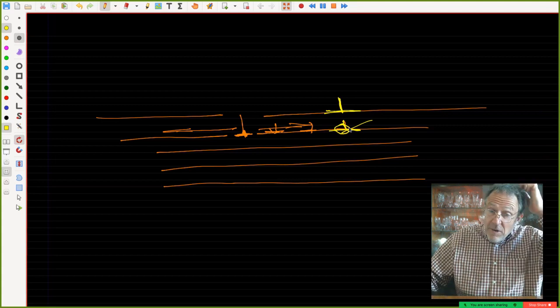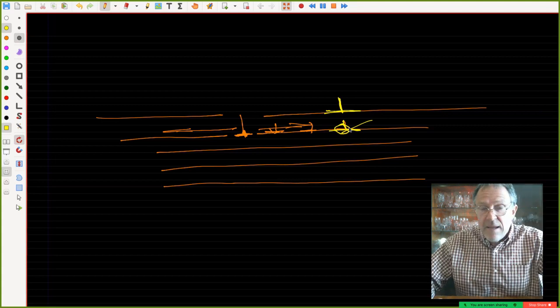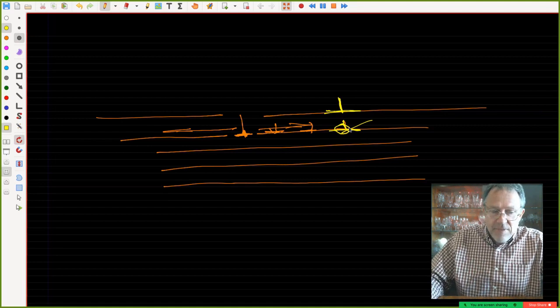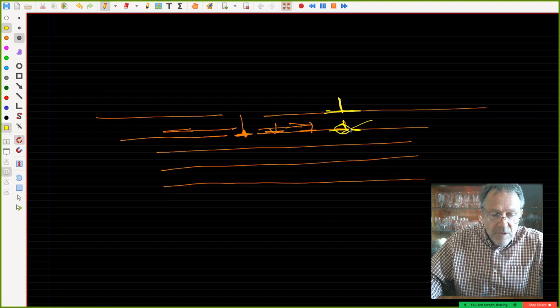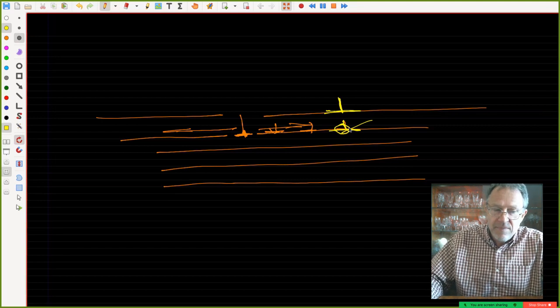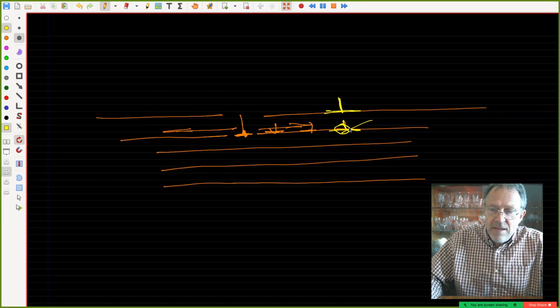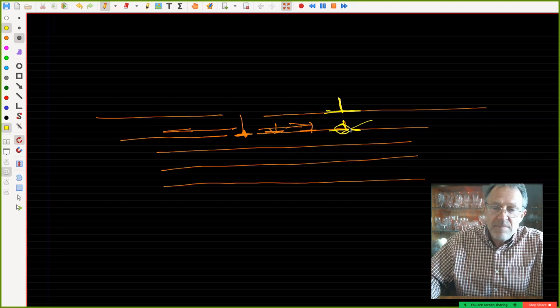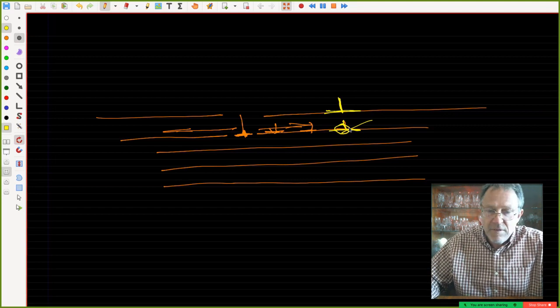So for edge dislocations we need the climb to change the habit plane of the slip, while for screw dislocations we can have this cross slip. And a cross slip is just we move from one slip plane to an inclined slip plane of the same crystallographic symmetry, or maybe even a different one.